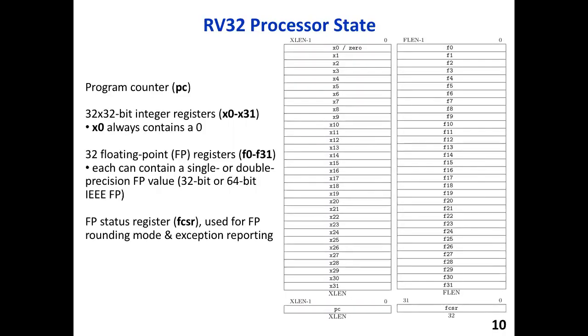So once you're doing that, you're basically taking the FPGA and using it as a CPU. And one could make a compelling argument, but gee, why don't you just buy a CPU and use it as a CPU? And I'd be like, yeah, you can do that, but then you don't get the ability to write your own instruction set architecture, which is really the kind of thing you might be interested in doing. To date, nobody at Fairfield University has been writing their own instruction set architectures, and with good reason. There's plenty of good ones out there. You need a good reason to write your own.